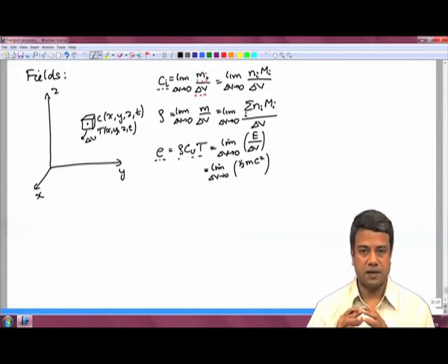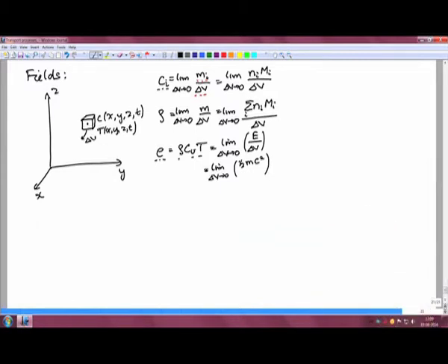And from the internal energy density, you write it as the mass density times Cv times the temperature, and from that you can define what is the temperature field. So, the fundamental variable in this case is actually the internal energy density or the enthalpy density, depending upon whether you choose working at constant volume or constant pressure.